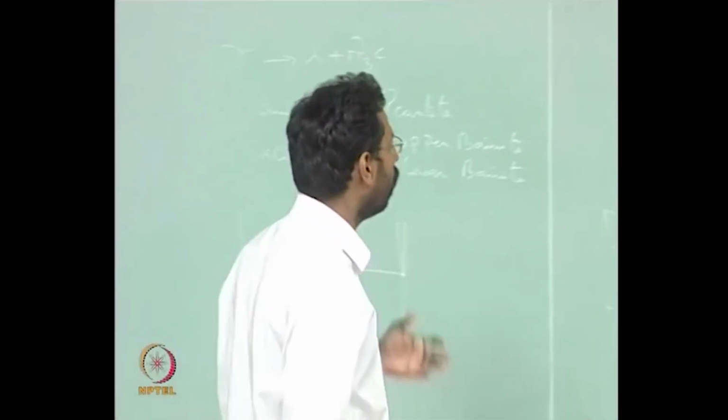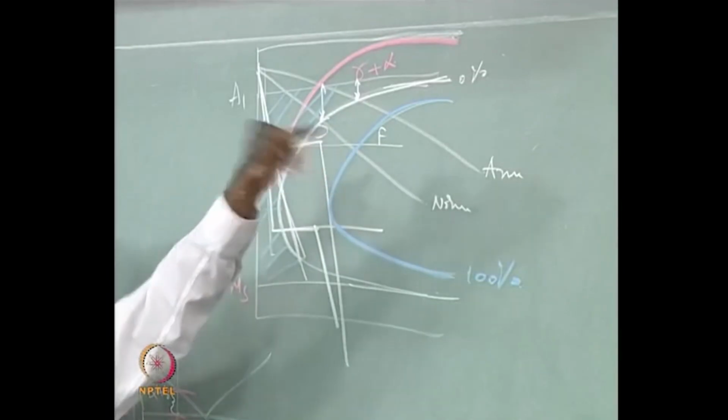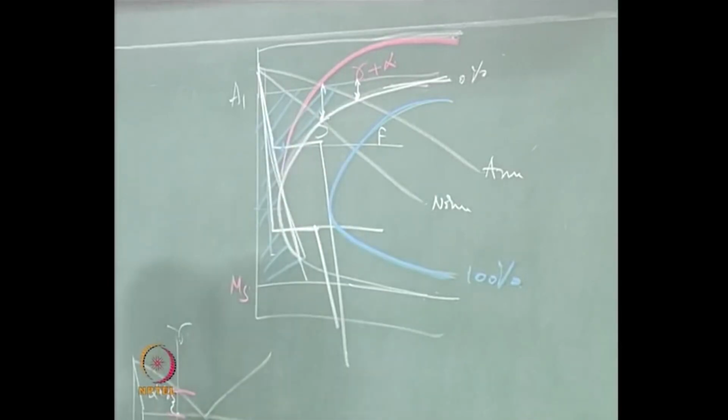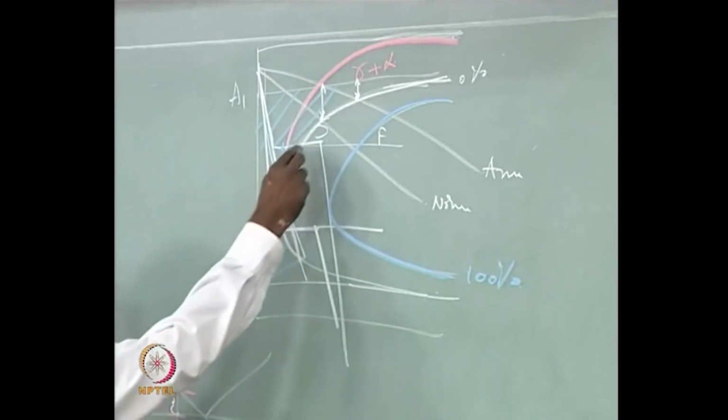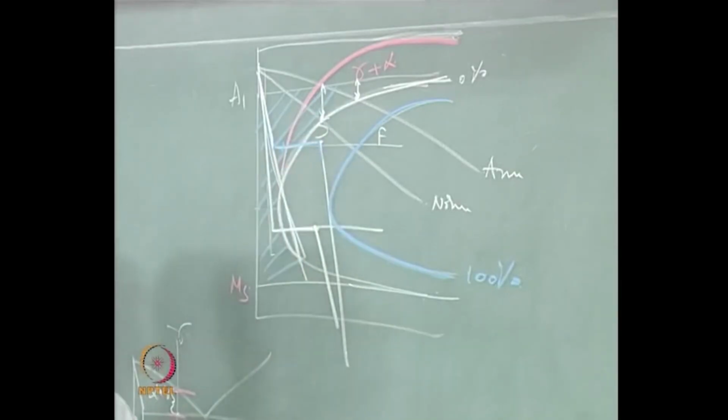So in principle the microstructure is much more accurate. So you keep on seeing the microstructure. For example, if a steel is quenched from here itself, what would you get? You get 100% martensite. If a steel is held up to this time and then quenched, then some of the gamma would have transformed to pearlite and the remaining gamma would give you the martensite.